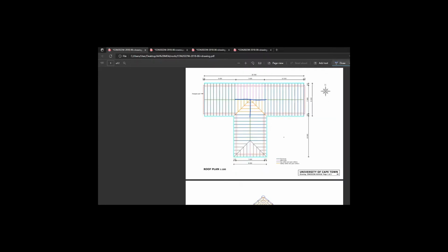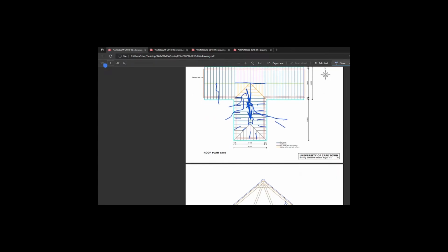All these tiles, they're lapped nicely, so they're nicely waterproofed. Water comes, runs down, it hits here, it runs down, hits here, it runs down. But if it hits the center and we haven't placed anything, it is going to enter the roof. So a ridge tile is basically a little cap to ensure that if water happens to land in the center, and we can assume that because it's rain, it will land in the center, it's going to hit the ridge tile and run off. Because all the tiles are lapped nicely, there we go, bounce, run down, bounce, run down. Everything is nicely lapped. There is absolutely no way for it to return under a tile. Well, I wouldn't say absolutely no way, there might be. I can't come up with the reasons why, but there might be.